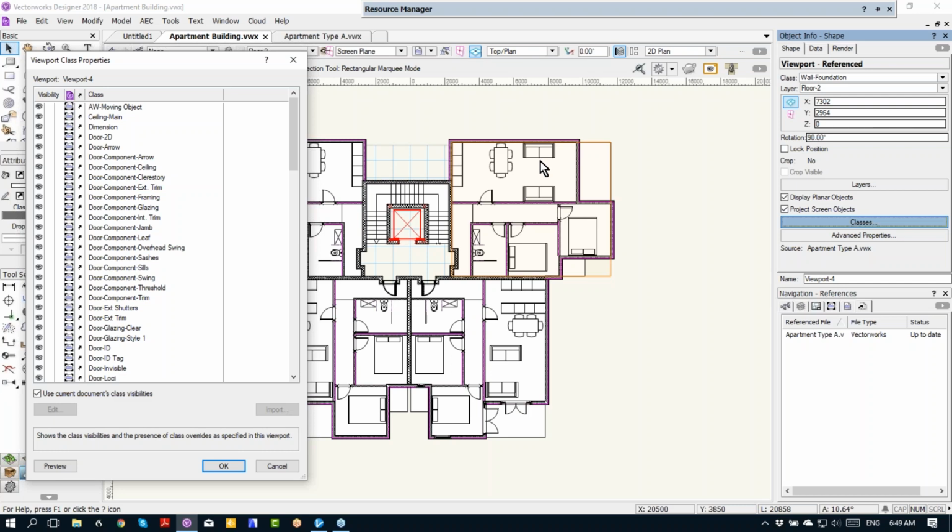And the multiple development might be better if you used a different file, because at least that way you can use fit walls to roof, you can build the roof on another layer, you can control the 3D model much better. And that's what I've tended to use with hotel type resort projects. You've got a site plan which has got a site model in it, I hope it's got a site model. And if you use a design layer viewport, or even if you use a symbol, you can still use center surface to get each symbol at its own elevation relative to the site model.